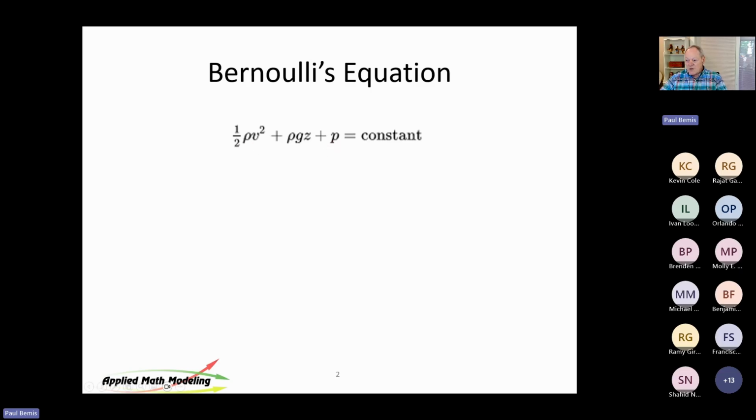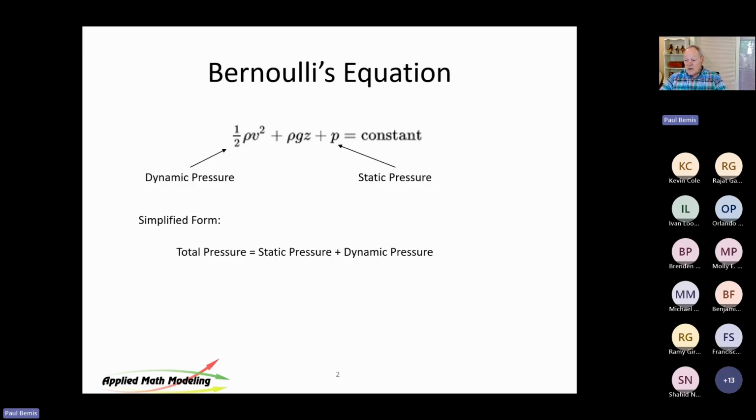This is a static pressure over here, and this is dynamic pressure over here. And it is those two in a data center, because we have no height in a data center, it is those two that combine to give you total pressure. And it is fairly constant. In fact, we model air as an incompressible fluid in the system. So total pressure is the sum of static plus dynamic, and you see those two variables right there.